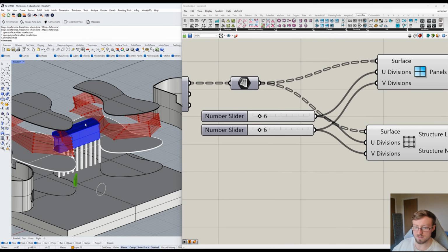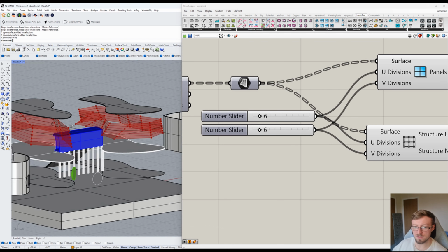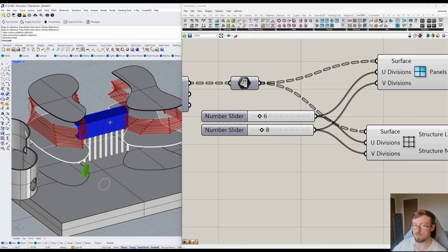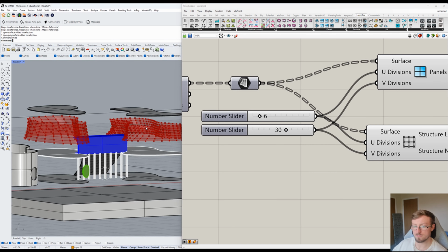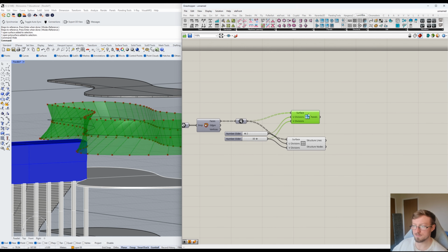So obviously we're trying to work around this curve, these curve shapes, and the lower the amount we have, the less geometry it has to work with, so it won't form that sort of shape. So the more divisions we put in, the more accurate it will get to getting around that original curve, which makes sense. Let's just do that.